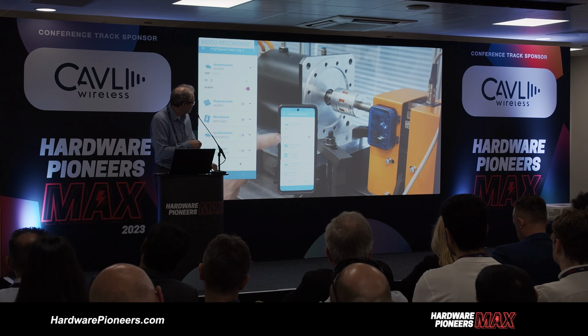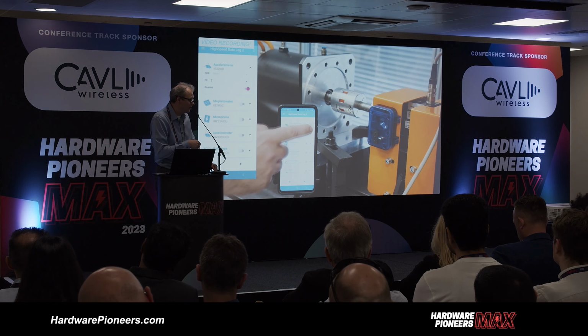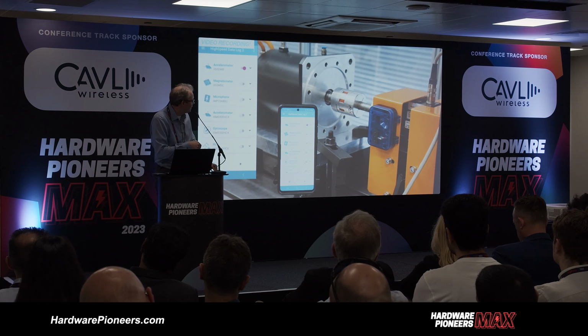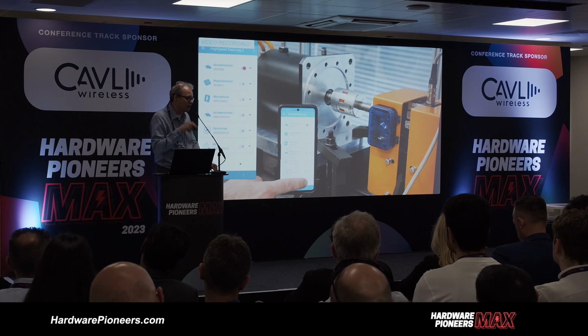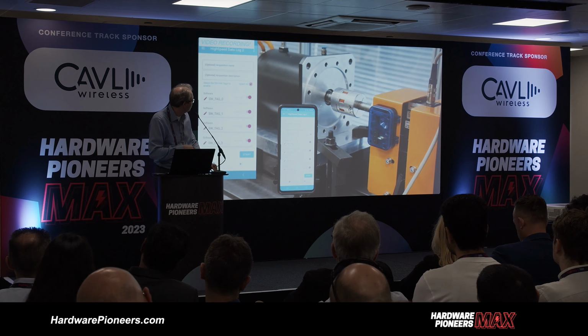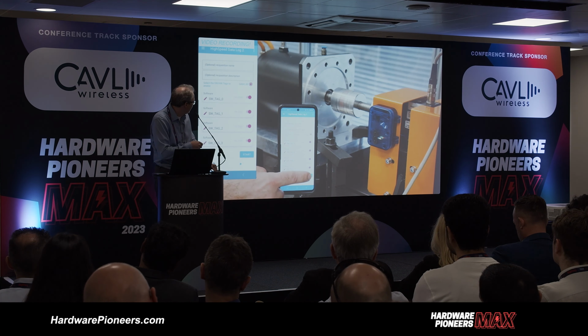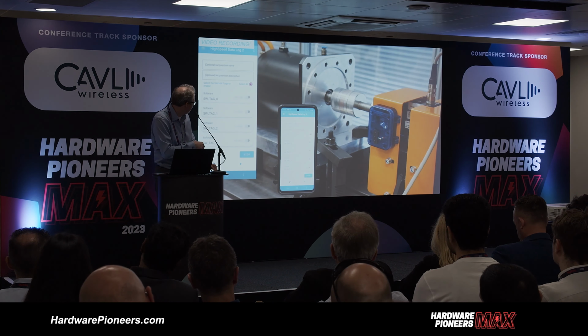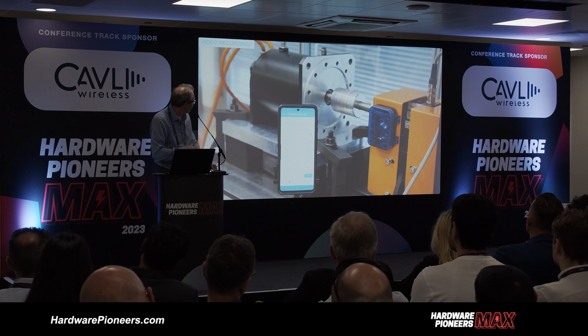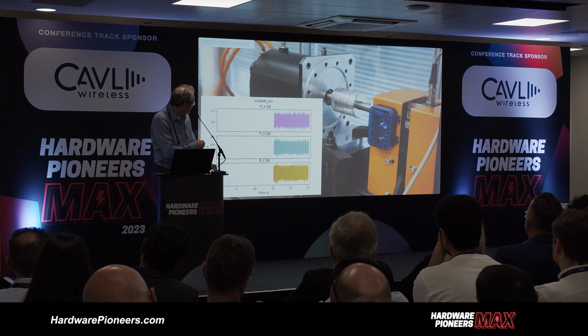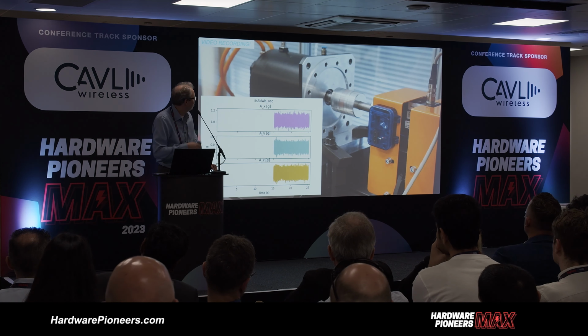We are now using this high bandwidth 6 kilohertz sensor, which is configured up to 2G of vibrations. And this is roughly what we normally see in motors specifically, that it's not that much higher vibrations. And now we just click the start button to make the logs. We put on the motor to spin at the same time. And then this is actually what you would get out from the Python scripts. So exactly these kind of graphs.